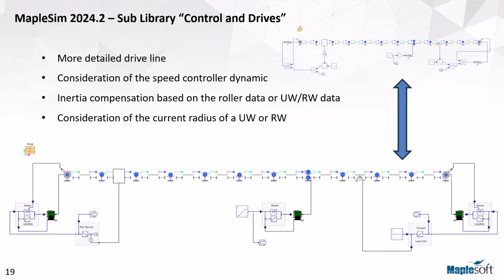And what is inside of these components? At first, the torque motor. It includes also a model of your driveline, which means you can define a gear ratio, you can define inertias from the motor, from the gear, or if known, also from the shaft. And it's possible to define motor losses here. And the speed controller, as I said, has a feed forward part at this stage.